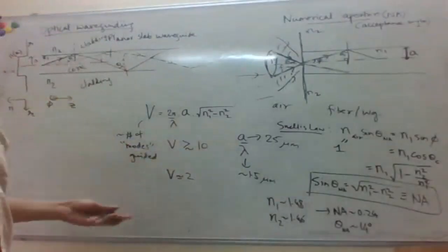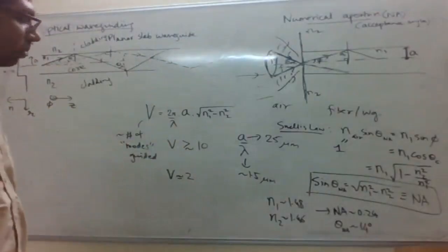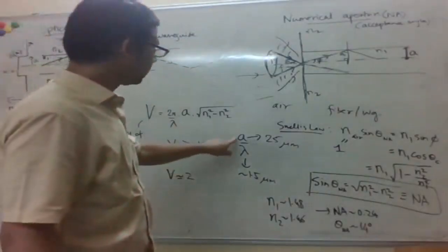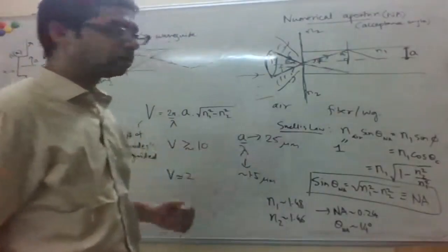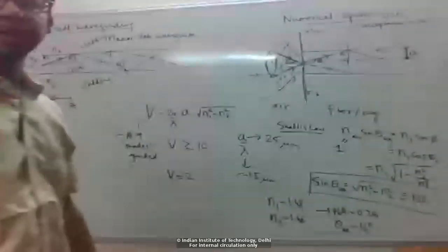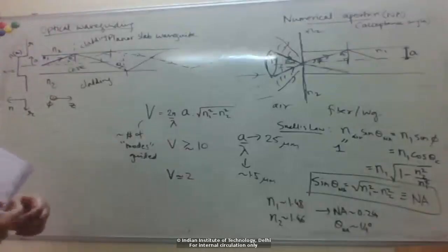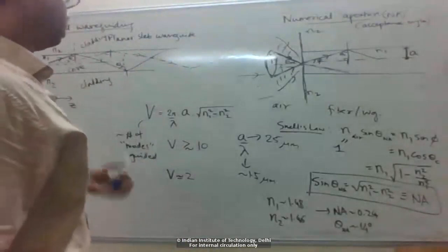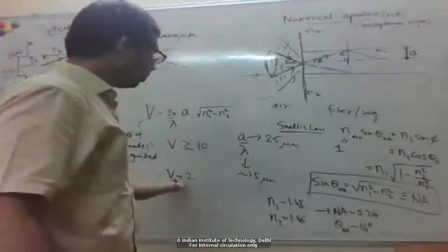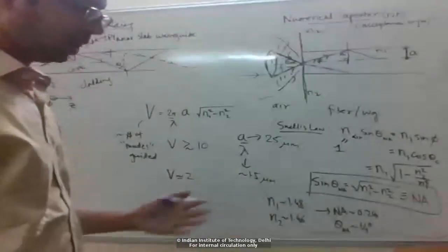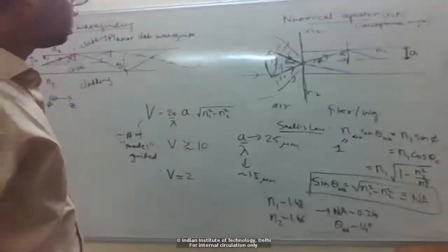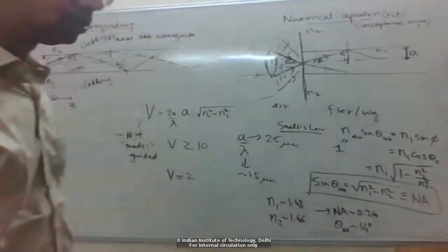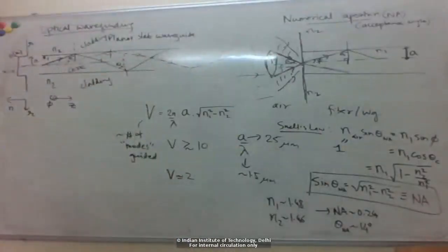If you look at commercial single mode fiber available today, the core radius is about, let's say, 5 micron, and the index contrast is around 10 to the minus 3 or so. And why do we need fibers with low V number, supporting only a single mode or few modes, compared to fibers with lots of modes? That we'll discuss soon.